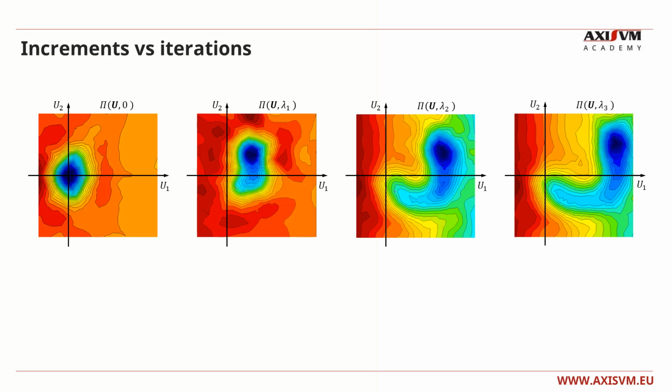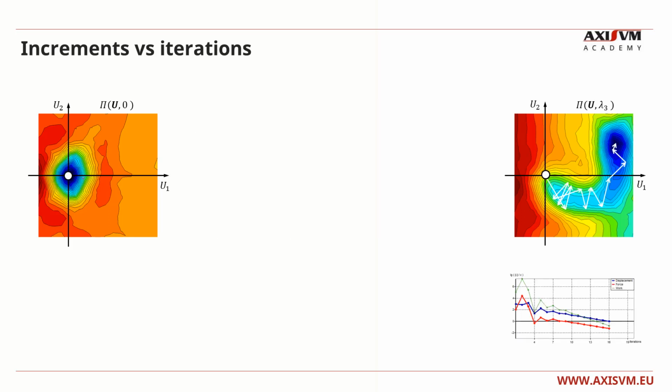Looking at the maps for the multi-degree of freedom case, it can be seen as well. Different map belongs to each load increment. Increasing the load level, the solution point moves far from the origin and the surface becomes more and more complex. Therefore, covering the long and bumpy way to the solution point needs a lot of iterations with weak convergence. Moreover, the convergence can be impossible due to an infinite alternating iteration process.